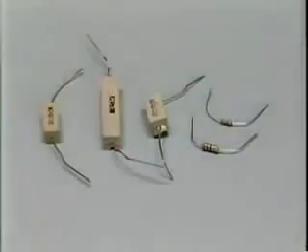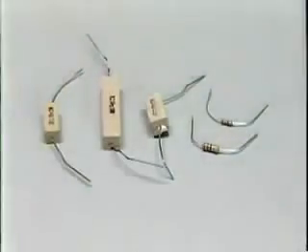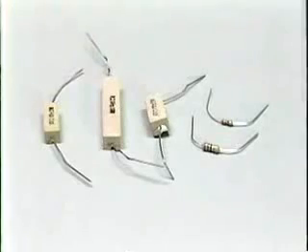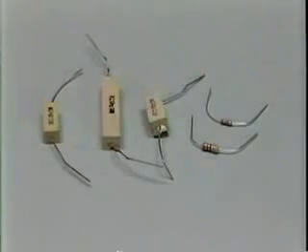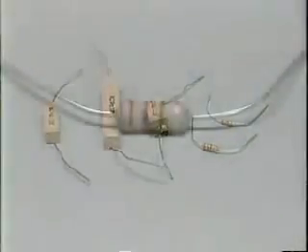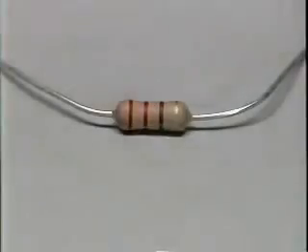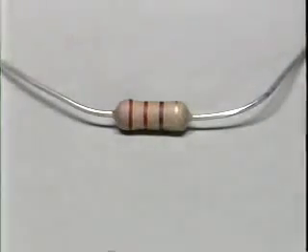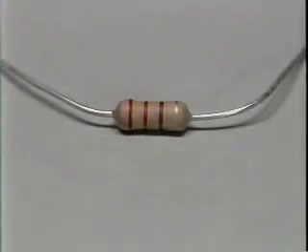There are many sizes and types of resistors. They are specified by their resistance value in ohms, according to their tolerance as a percentage of the nominal value and by their power rating. The resistance values and tolerances of resistors are normally indicated by a standard color coding system. On each resistor, we find 4 colored rings.